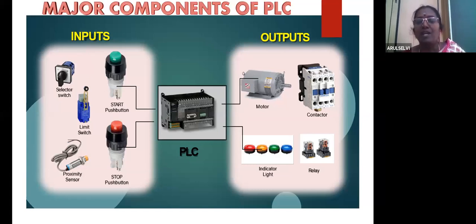So that is why we are using an output module. Okay, children. We are using an output module attached to the PLC, so that 24 volt or 120 volt operated relays can be connected to the output module, and through the relays the motor or furnace or any field device can be connected. Okay, let us see further. If any doubts are there, we'll see.